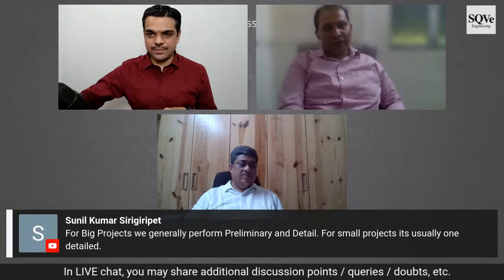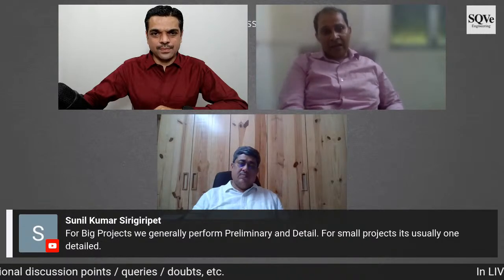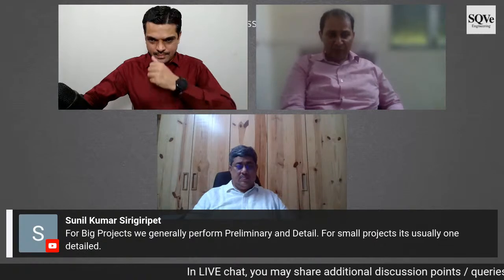So basically, what we can do is, I don't know what size you are visualizing with these small investigation projects, even if you are saying 4 to 5 boreholes, you can complete 2 boreholes, come back to the structural consultant, discuss the probable type of foundations and what can be done, and again advise the geotechnical investigation team to further plan accordingly as per the conclusions of the discussions with the structural consultants, the type of foundations we are proposing, or maybe increase the depth of boreholes at that point of time, or increase the number of boreholes, and then take it forward.